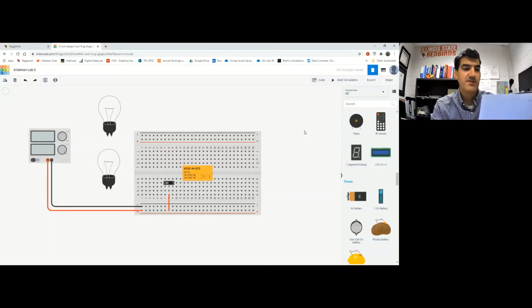And the next thing I'm going to do is go from the output side of my selector or slide switch to the input side of the coil. All right, so the output of my selector switch, I'm going to use this side. It doesn't really matter for my slide switch, but I'm going to use this side, and I need to go to the input of the coil, right? The positive side of the coil. So that is going to be pin 16, which is right here.